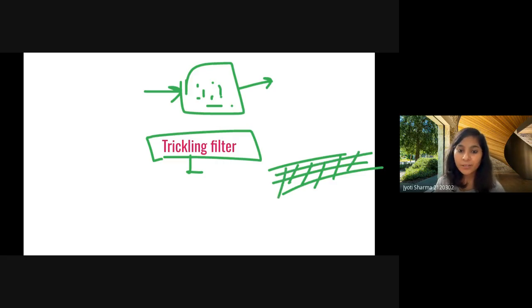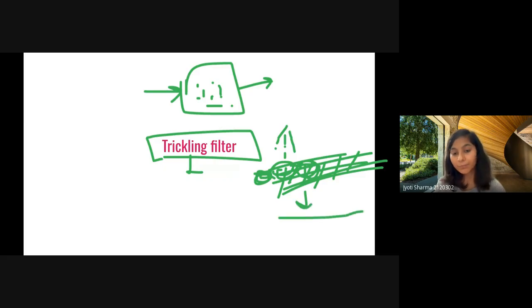It may be this surface is of stones, let's say, and on that we have the layer of microorganisms. Then the wastewater will be trickled into that, and the polluted water will have to cross this layer of microbes.